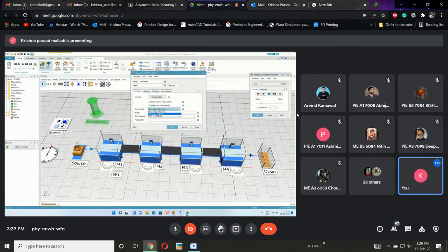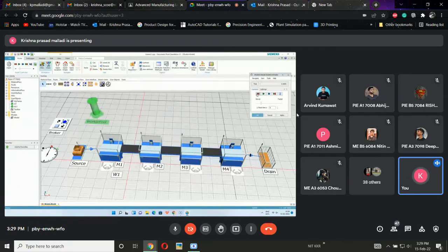Okay, clear? Now we have done the first part, move freely within work area. If we click this one, what will happen? If you run the simulation, the worker will take the shortest route for this mission, go to that location and do the assigned work. That is exactly what happens if we assign this one. Clear? They won't follow any conditions here. The limitation is, if I don't want to move my worker between these two, it is not possible. The worker will calculate his own distance and move. That is freely moving work area.